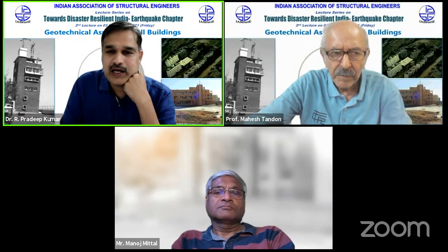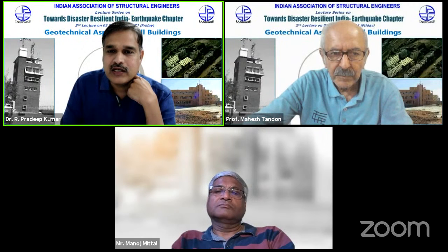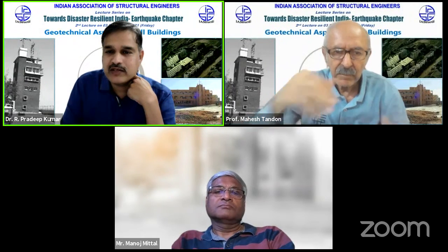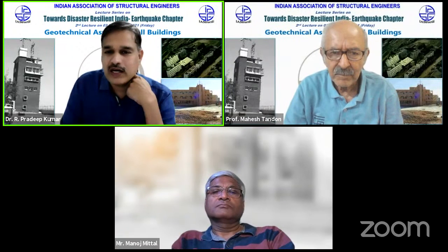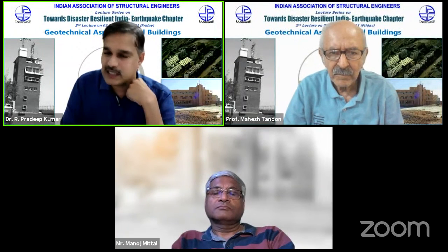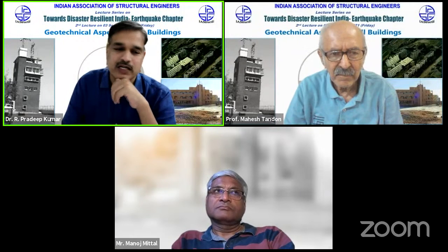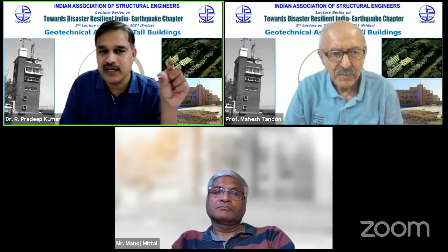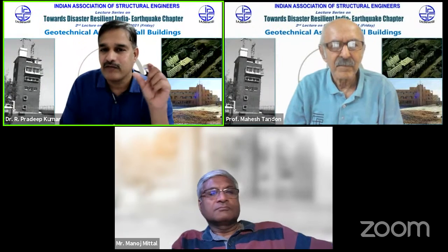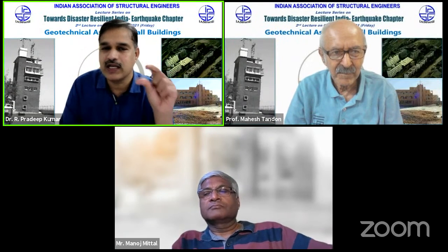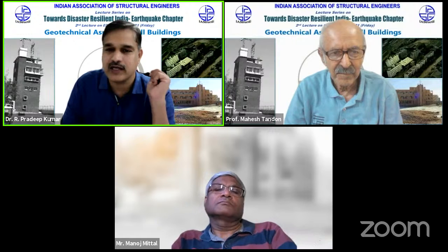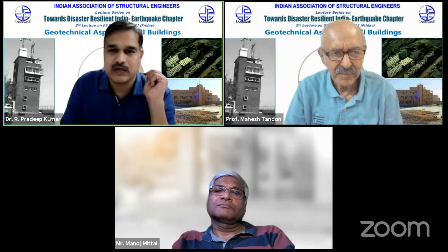In pile cap and pile foundation for tall building, as per Table 1 of IS 1893, can I take benefit of increase of pile vertical and lateral capacities in earthquake case? Yes, Amit Patel, we can take advantage of that. But the only thing is, if there are liquefiable layers in between, we cannot consider those layers in the analysis. So yes, you can take advantage of that.